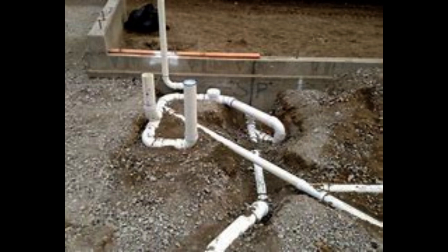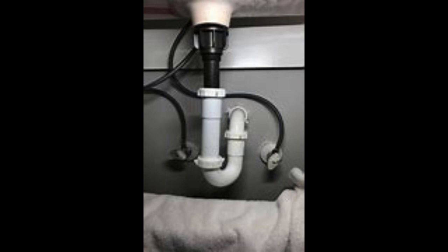D. Gas distribution systems. 1. The inspector shall A. Report: 1. Location of gas meter, and 2. Visible material used for gas distribution system. B. Report as deficient: 1. Noticeable gas leaks. 2. The absence of a gas shutoff valve within 6 feet of the appliance. 3. The absence of a gas appliance connector or one that exceeds 6 feet in length. 4. Gas appliance connectors that are concealed within or extended through walls, floors, partitions, ceilings, or appliance housings.